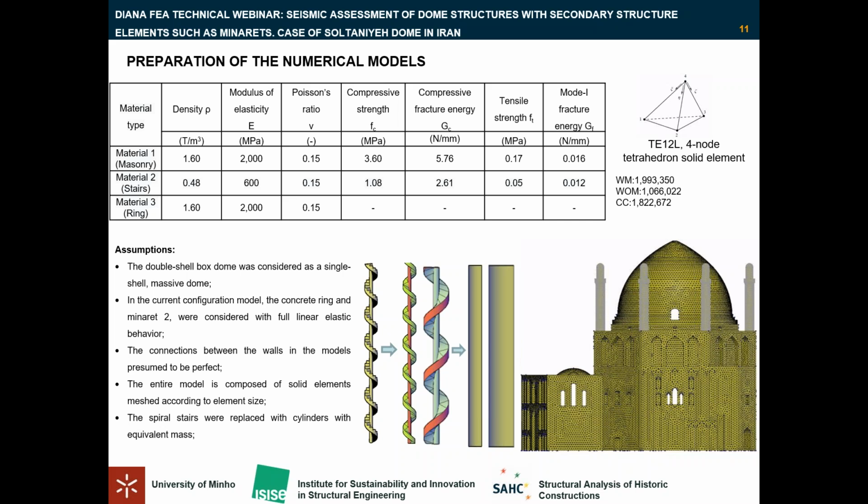In order to optimize the number of elements of the model, mesh refinement was carried out automatically and manually. This process considered crucial aspects for an accurate numerical model, such as the number of elements along the thickness of the structural element and overall mesh optimization.